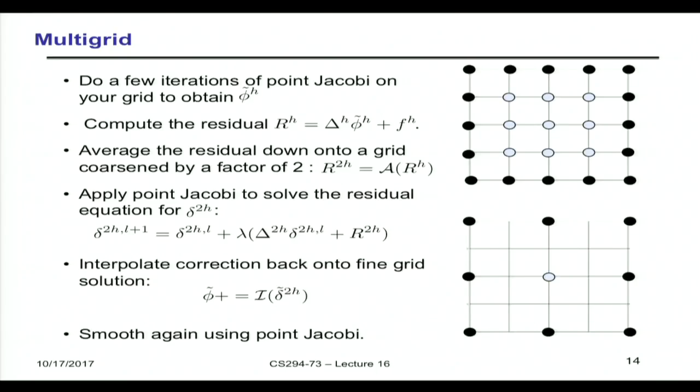And so when you put all of that into this correction equation, you now have 2H, a twice as coarse grid. You have the residual that came from the finer level, and now you're going to do this point relaxation sweep. One important thing here, though, is that lambda is a function of 2H, no longer of H, because I can take bigger steps. And basically keep doing this. If this were the whole domain, after one coarsening, I only have 1 degree of freedom, right?